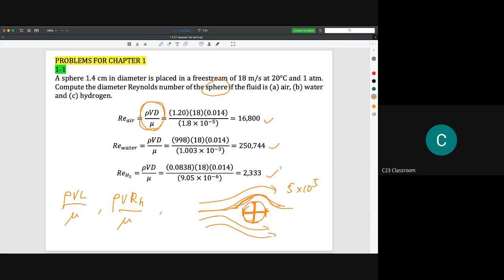Another thing is, I hope you can remember the common parameters for common fluids, for example air and also water. The density of water is almost 1000 kilograms per meter cubed. It is okay for you to use 998 or 1000, but at master level, we assume that you are starting your master project, which is quite specific work. So you need to base your calculation on the temperature.